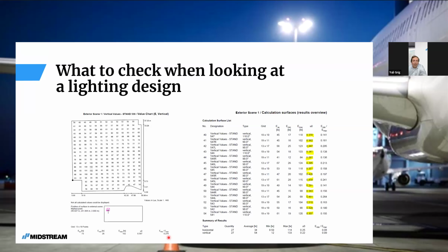Yeah. And I think, if somebody wonders, why isn't it all exactly the same? Why isn't it just like a blanket of light on an aircraft stand? That's presumably because we can't illuminate from both the front and the back. Having a uniformity of one is like a utopia. It's not effectively possible, because you're always going to have a little bit higher intensity closer to the light source. Let's say that when you go close to or above 0.5, you start not to notice any sort of difference. So for you, it looks exactly the same.